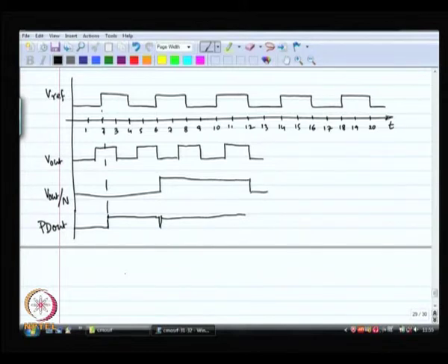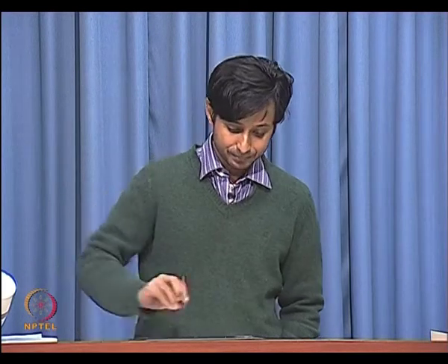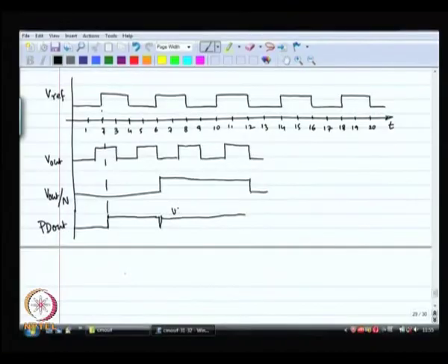This means that the phase detector is telling you that, hey, you need to increase frequency, this is up, you need to go up in terms of frequency. So, the VCO responds and goes up in terms of frequency, because the up signal is coming. Up signal is coming means that the control voltage is increasing.